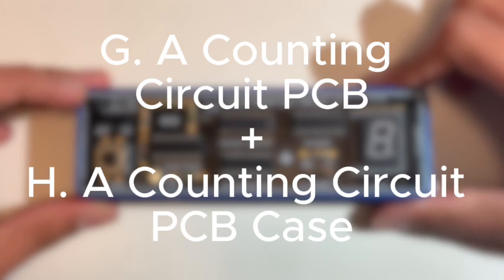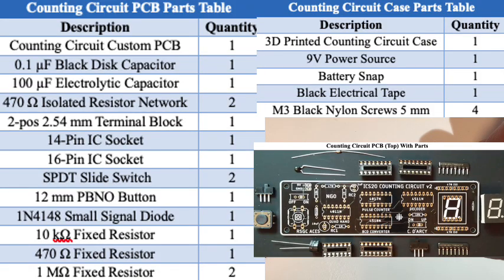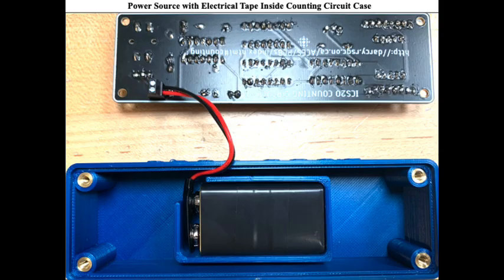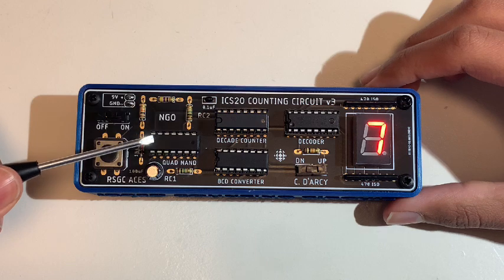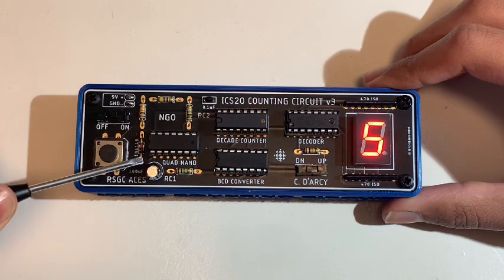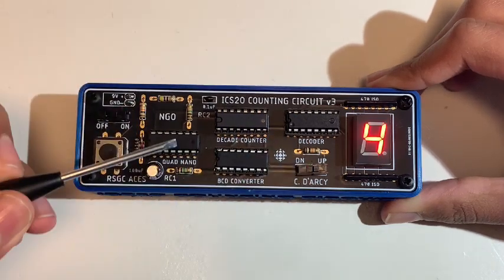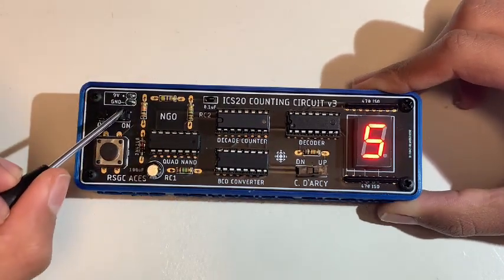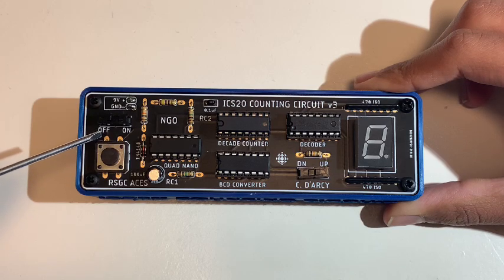The single-digit counting circuit breadboard prototype is converted into a compact, practical version on an encased custom PCB, with these parts soldered on. A battery covered with electrical tape inside connects to a terminal block, powering the circuit. It functions exactly like the breadboard version, but uses a larger capacitor in RC1, making it count longer. This version still has an up-down switch, and now has a new on-off switch. However, it cannot be preset, reset, or use a display test, blank input, and store functions, and lacks adjustable speed.